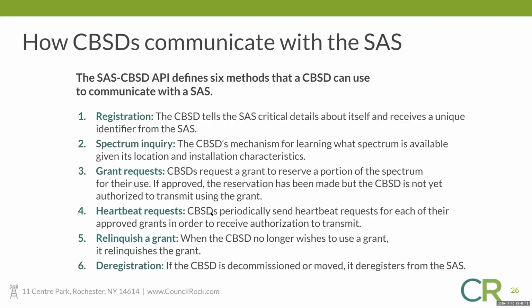And once you start transmitting these, then you will be allowed to receive authorization from the SAS to start transmission. And once you have the authorization to transmit, you just continue to operate as normal. You still need to send the heartbeat. If something changes because you're in a region where there is an incumbent that is going to come up, because you're in the coastal, any of the coastal lines, or you're close to a fixed satellite station and you need to do something, you're going to get some information from the SAS, and the SAS is going to tell you what you need to do.